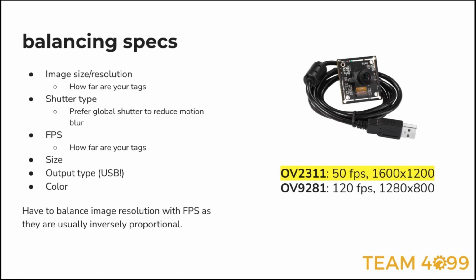The last is color. When you're doing Apriltag detection, the actual algorithm behind it never works on color. It only works in monochrome. So it's really important that either you select a camera that is doing monochrome immediately on the sensor itself, and then the image it's sending off the camera is monochrome, or you're doing the processing off board in your software.